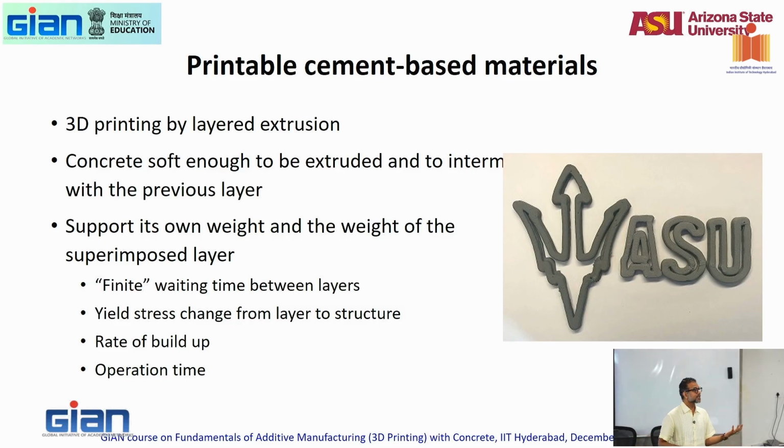Lots of advances in admixtures happen because of that. Lots of advances in pumping technology. What happens when you have high shear flow within a pump? We never had to do that with concrete. All you had to do was mix in a mixer and place it right there. You never had to know what happens when you pump concrete through long distances, right? Pumping high shear flow. The whole idea of shear flows came through. We will use all of that in our understanding of how you can 3D print concrete.